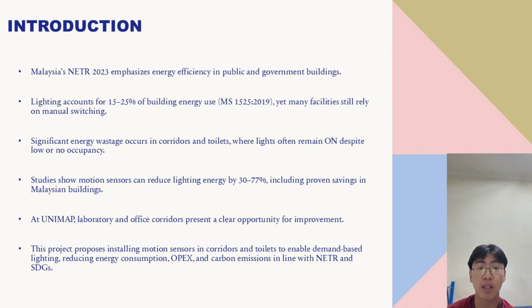In educational buildings, the highest non-critical energy waste occurs in areas like corridors, staircases, and restrooms, where lights often remain on even when there is no occupancy. Studies show that installing motion sensors in these areas can reduce lighting energy use by 30 to 77%.